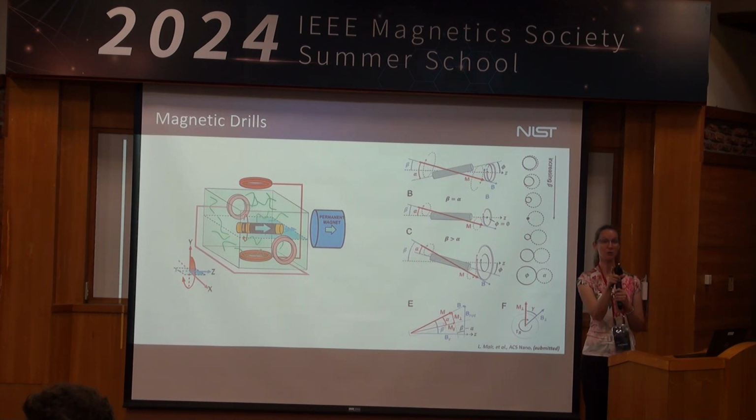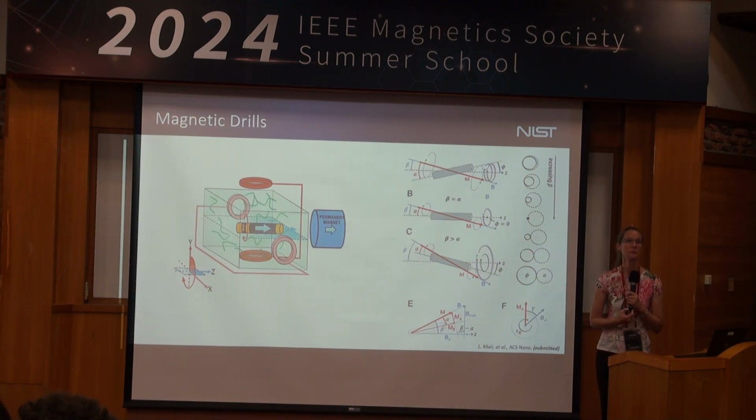You can change that angle, and so you can make them look like they're tracing out different kinds of circles, but they're all basically acting as a drill. It's highly repeatable. You change the magnetic field gradient, you're going to change the speed at which it happens. You change the rotation speed, you're going to change the speed at which they rotate. It all becomes controllable. You were talking about using it in some magnetic robots. Yes, so this would be a magnetic robot.